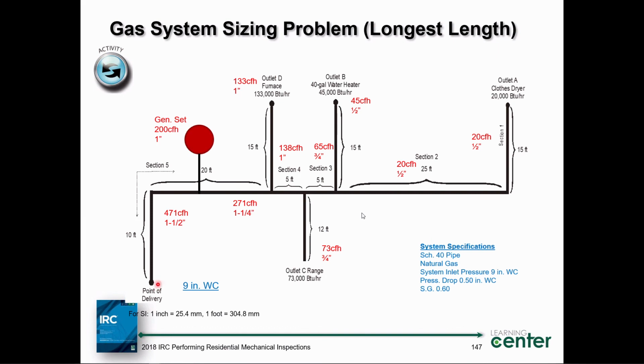You're probably going to have to replace the meter based on this load here. You never know, but it's not in the code. If you're a contractor, you need to talk to the utility company at that point, because the volume of gas that's now supposed to go through your system to supply the demand has gotten a lot greater, hasn't it? So we don't do anything with the utility meters, but it's just a point of interest, right?